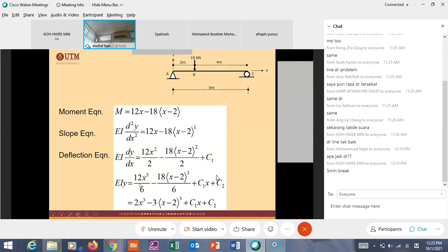And proceed. This one is deflection. Again, integrate this one as a variable. So it becomes 3, and this one 3 here. 3 minus 2 as 3 multiplied by 2, 6. And this is as usual. The only difference here is when there is a continuous function. Then this is the EIy.